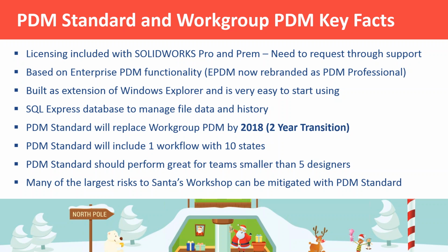There are a lot of limitations to PDM Standard. I'm not going to run through them all today, but one of the big ones is limitations to the workflow. You're only allowed one workflow, with 10 states in that workflow. But it will work quite well for smaller design teams from a performance standpoint, especially if they're just doing SOLIDWORKS data. There are many reasons why you'd consider PDM Pro if you'd like to revision control more than SOLIDWORKS data. And just to reiterate, a lot of the largest risks are mitigated with PDM Standard. Anything to include there, Mark?